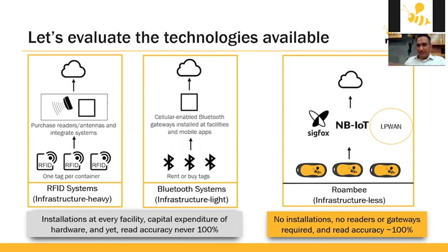It even goes down to details such as installing the antennas to face a particular direction when the goods are moving in and out. So if, for instance, the forklift does not move through that particular gateway where you have set up antennas, and they take a roundabout route, you're probably not going to be able to sense that returnable container being checked in to your facility. So RFID has never been able to solve this problem entirely.